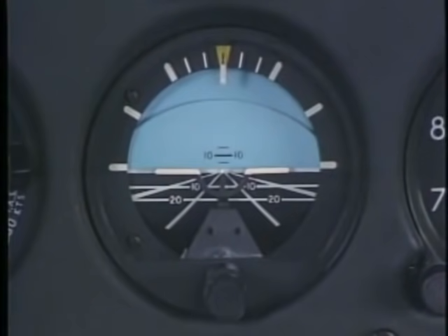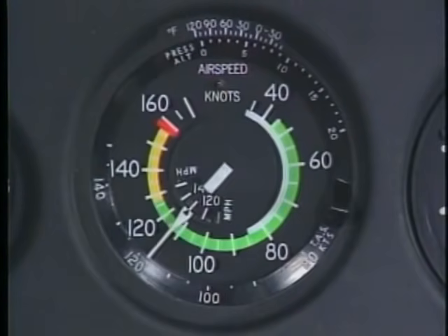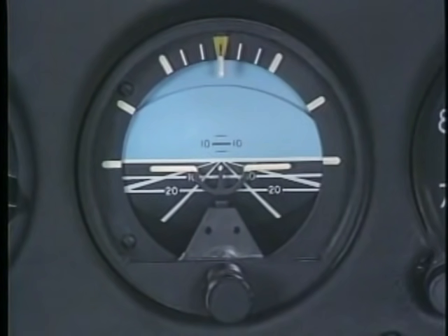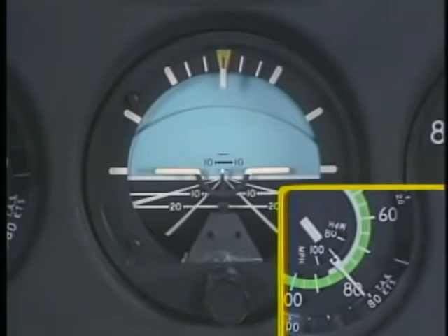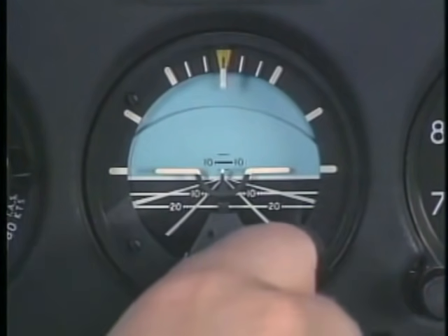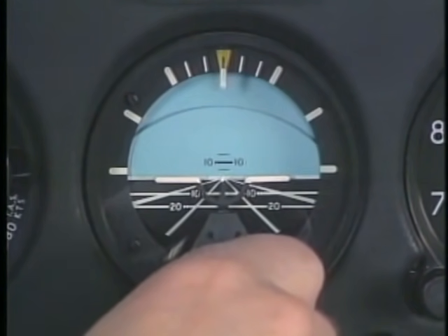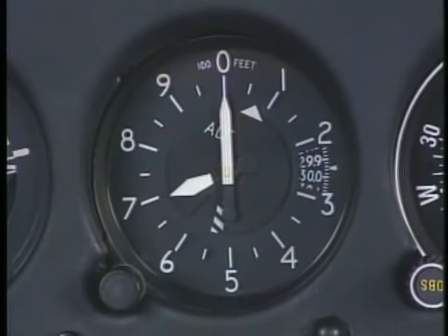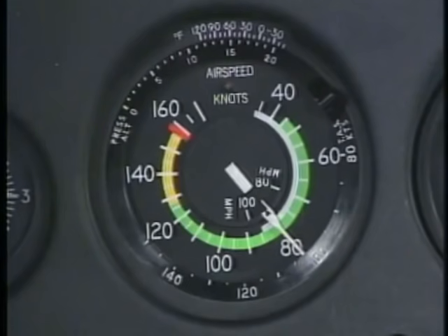In straight and level flight, maintain altitude by establishing the appropriate pitch on the attitude indicator. Normally, the miniature airplane is aligned with the artificial horizon. However, if you increase the airspeed while maintaining level flight, the miniature airplane will be below the horizon. At slower airspeeds, it is above. After you've established level flight for a particular airspeed, you should reset the miniature airplane so it is on the horizon. After the correct attitude has been established, confirm level flight by referring to the altimeter, vertical speed indicator, and airspeed indicator.